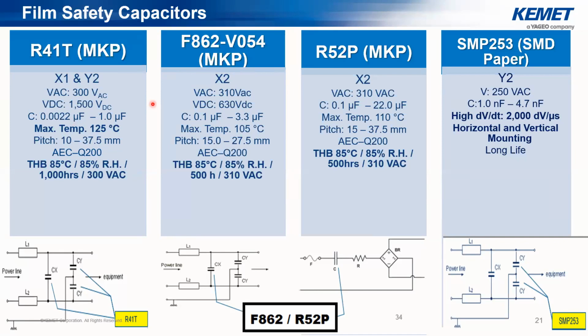But it has two slight disadvantages. First disadvantage is its behavior at high temperatures. The second disadvantage is that it's a little sensitive to moisture. And this has been a bottleneck in the designs of many engineers: how to use a polypropylene capacitor if you really need high temperatures and less sensitivity to moisture. And this has been the bottleneck that our R&D for film capacitors has tried to address in the last few months. And we have come up with many interesting updates, not just with safety capacitors, but also with DC link capacitors, which my colleagues would be explaining to you in the next sessions.